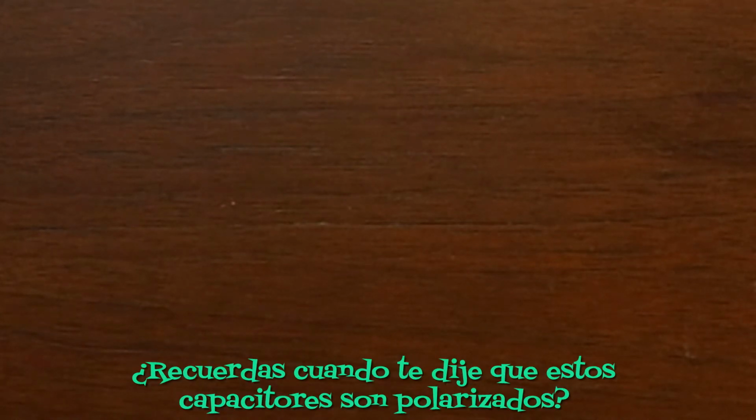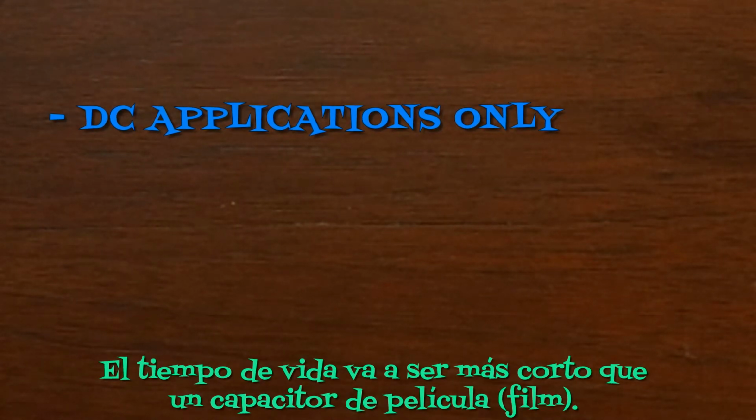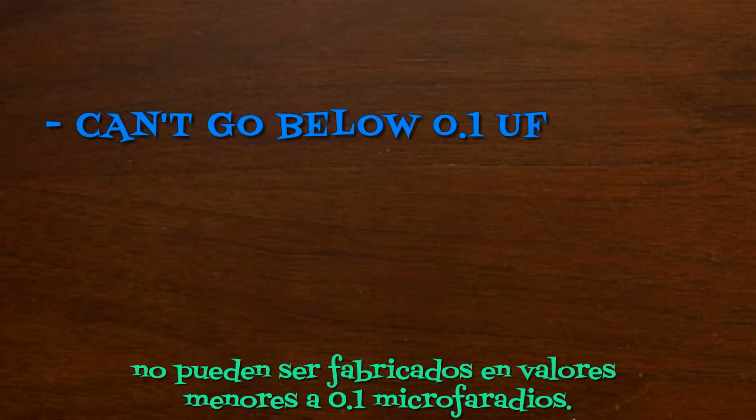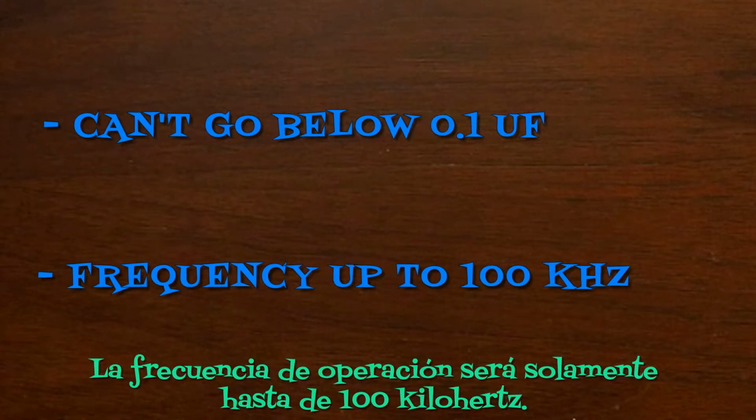I'll give you the downsides first. Remember when I said these caps were polarized? They're only good for DC applications as a result. The life expectancy is going to be shorter than a film cap. Electrolytics are also limited in their capacitance range. They can't be made below 0.1 microfarads. We're only looking at an operating frequency of up to 100 kilohertz.